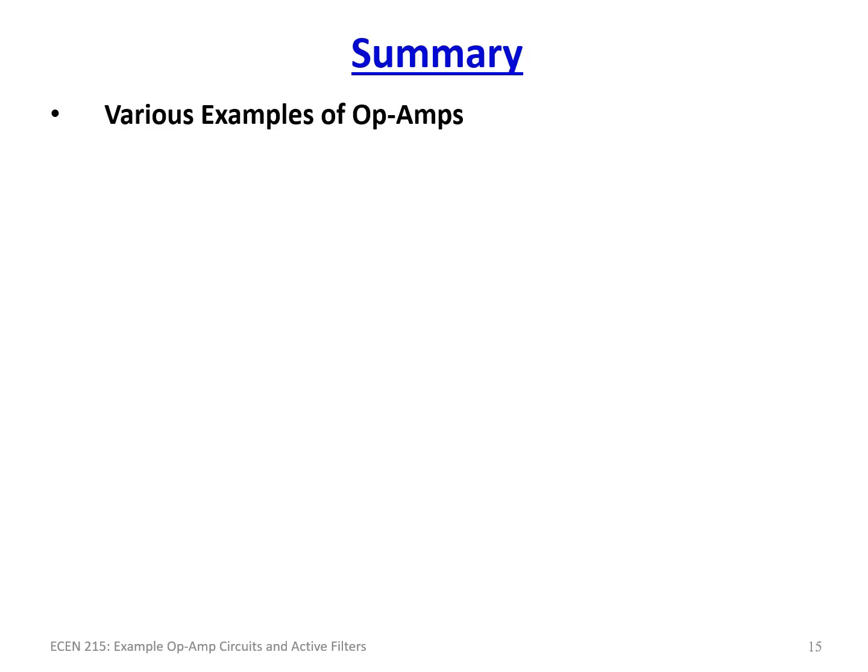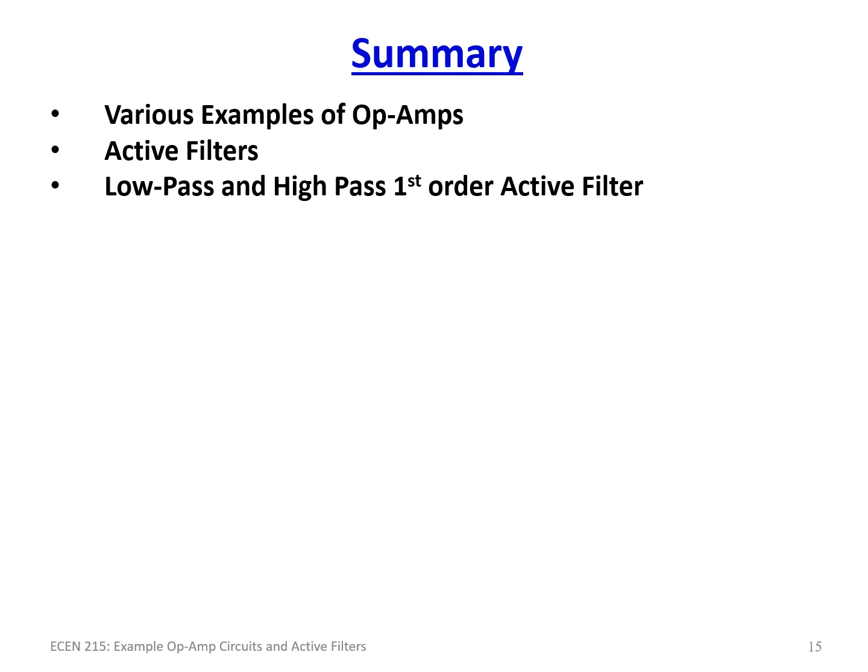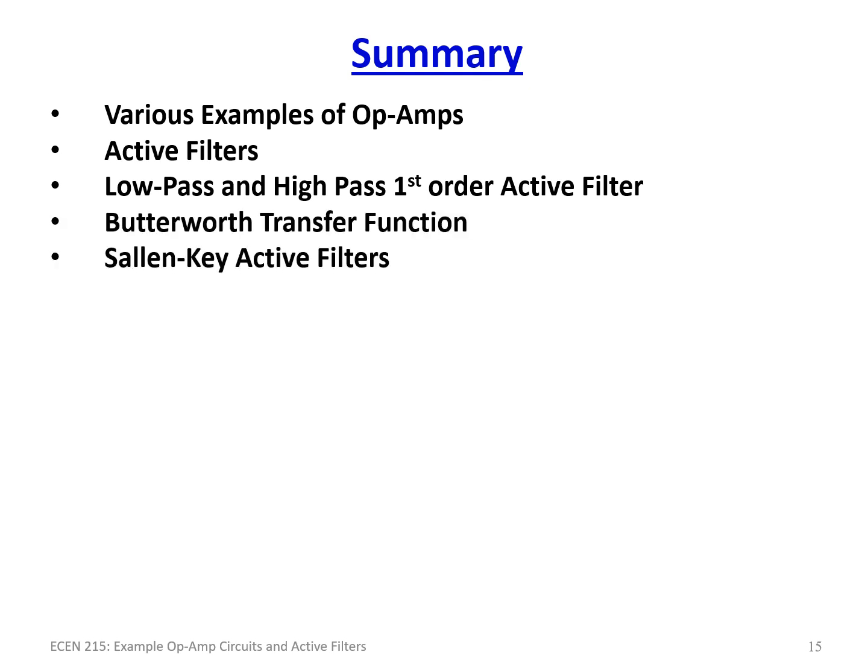So in summary today, we did various examples of operational amplifier circuits where we were given equations and had to build the circuits, or given a circuit and had to come up with the equation. We looked at active filters and what they are, what they mean. We looked at a low pass and high pass first order active filter. We looked at Butterworth filters and their transfer functions, and we also looked at Sallen-Key active filters, specifically the Sallen-Key low-pass filters and fourth order double-stage Sallen-Key